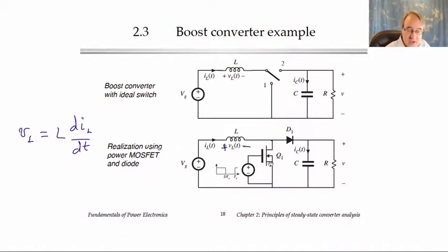When the MOSFET is on, we build up some positive current flowing through the inductor and through the MOSFET. When we turn the MOSFET off, we're effectively trying to interrupt the inductor current. The inductor current that was positive is now being forced by the MOSFET turning off to go immediately to 0. So what is diL/dt?